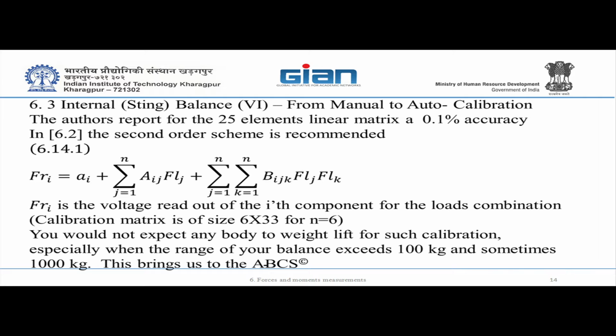But one thing this machine cannot do is make your balance better. We discussed it. If your balance is wrong, the strain gauges are not glued well or not located well, stiffness is not calculated, the connection is not good, this machine cannot fix that. The accuracy of the machine very much depends on the quality of the balance you're giving it. It's not standing by itself.